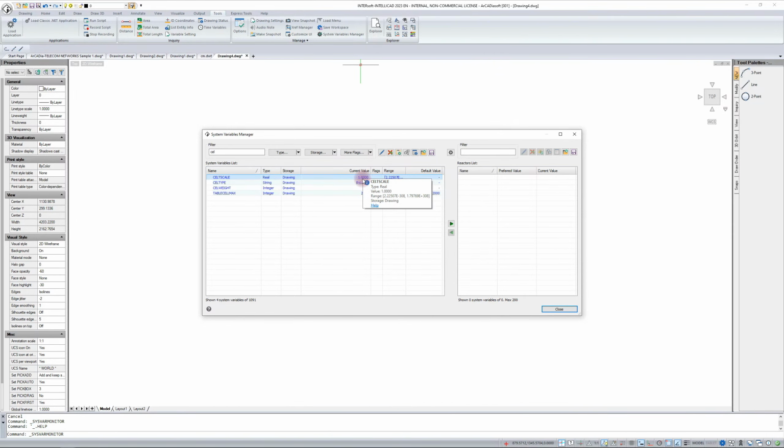The default is that there is the scale 1, and when we enter a dashed line, it looks like a continuous line. If you have to change that line scale every time, then it's a good idea just to change the value here before you even save the drawing template there. Let's change this value, if we already know it. Let's remember that this template is blank, so that no drawing element, no line, no polyline is there. Then let's define another value.